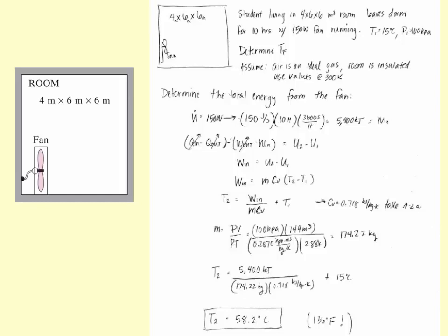So it can be an iterative process. In this case, the 30 degrees Kelvin difference is probably not going to be a problem. We're just saying, okay, I'm going to use a value that is close, and then if you iterate and solve it again using an average value, knowing the final temperature, and you get approximately the same final temperature, then you're okay. But you don't have to do that on this problem.